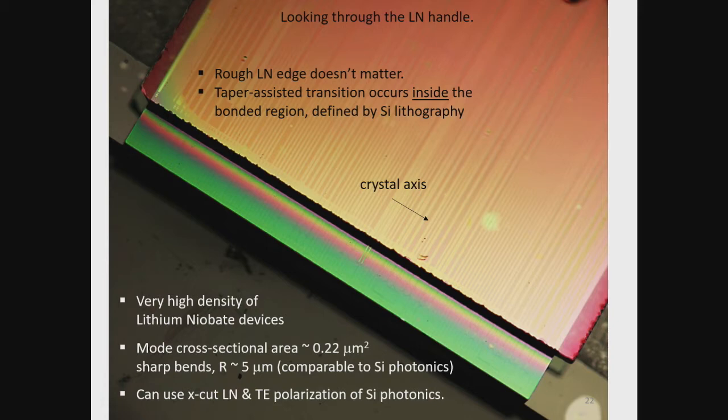Looking through a microscope, what you basically see, I hope this is in focus, you can see lots of these waveguides coming in, pure silicon photonics with an oxide cladding. And then it transitions underneath here. Now, silicon is the highest refractive index. So what this means is that the light remains in the silicon waveguide if it's wide enough, if N effective is high enough, as it goes underneath this edge.